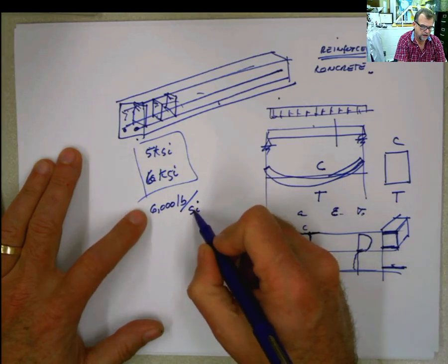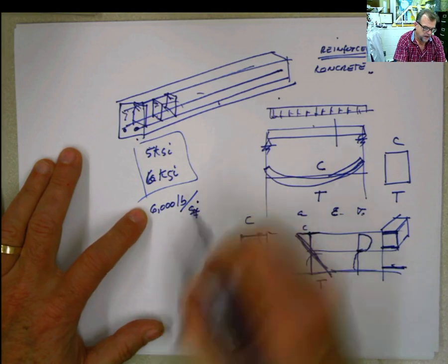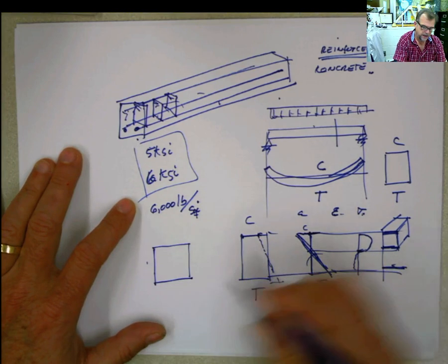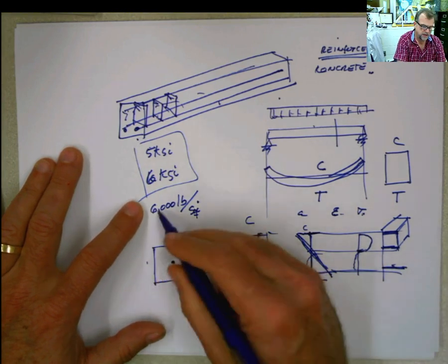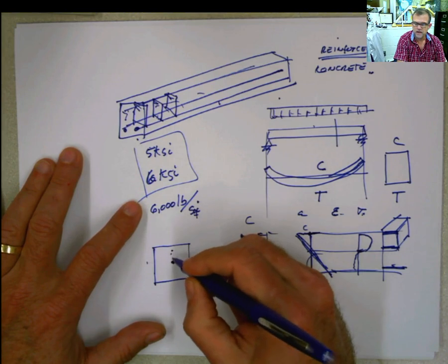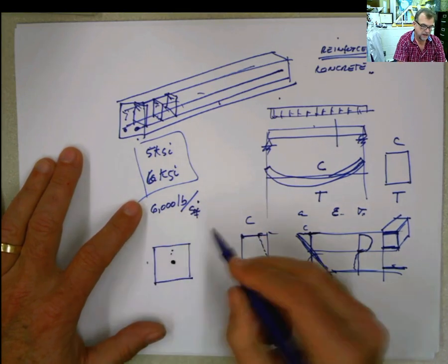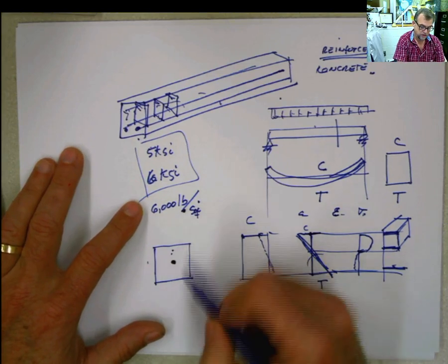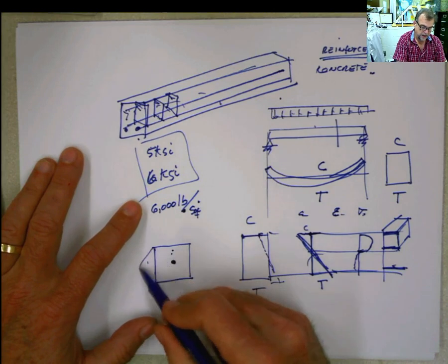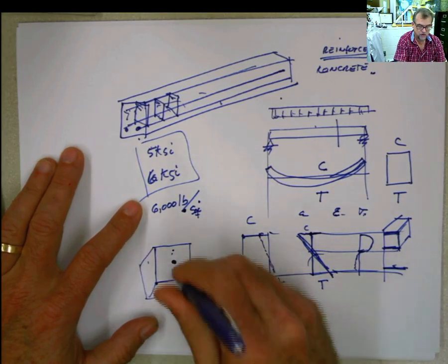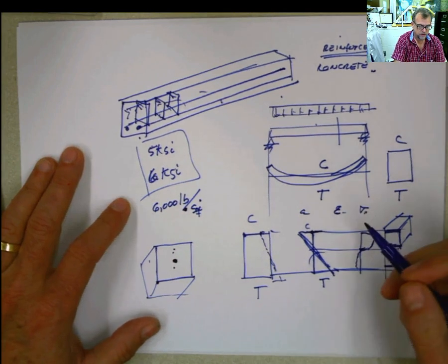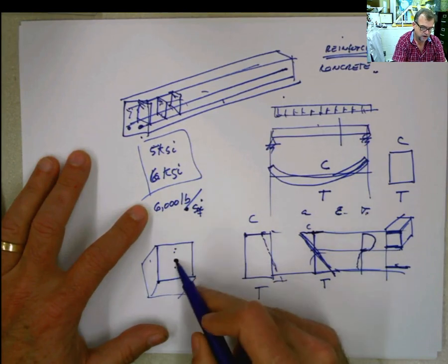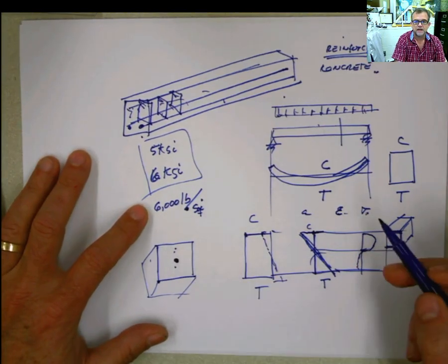Why is that a lot? Well, imagine 1 inch by 1 inch. This is the area, and on top of that I'm putting 6,000 pounds, 3 Volkswagen cars, for example. That's a typical value for concrete to resist in compression. That's a lot. A little cube like that with 3 2,000 pound cars on top of it, and the block is still resisting that.